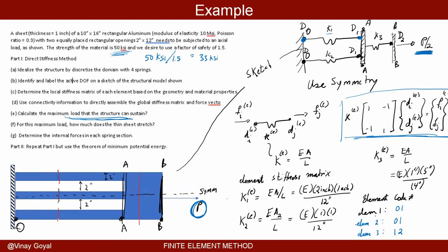So the area connecting node 2 with node 3, that's what you mean? No. I was comparing where the professor drew the red lines on the left, where the material is cut out. Because there's a smaller cross-section area there, we would have a higher stress in that area.